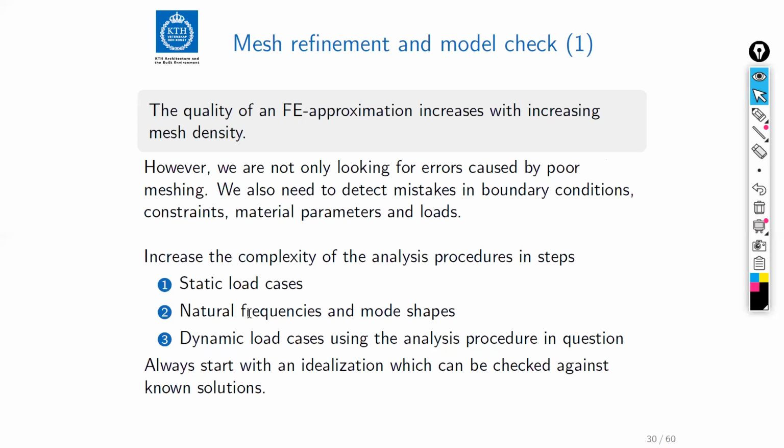Then, when we are happy with all of these things, only then do we start to apply the actual dynamic load cases. If we are doing this in a time domain analysis, using an implicit or explicit method to integrate the equations of motion, if it's a fairly large system, this third stage will be the most time consuming part. So before we start that, we want to be as sure as possible that everything is okay with our model. So we don't spend a lot of time waiting for a solution that in the end turns out to be erroneous, and we could have figured that out before.